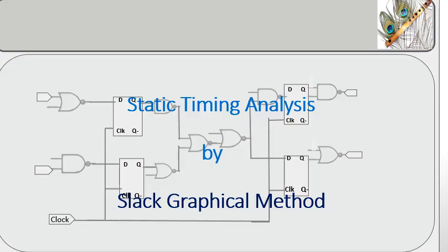Forward and backward graph traversals are superimposed to capture path delays. This visualization helps identify critical paths and dominant delay contributors. Thus, the slack graph becomes a powerful tool for timing debug and closure methodology.